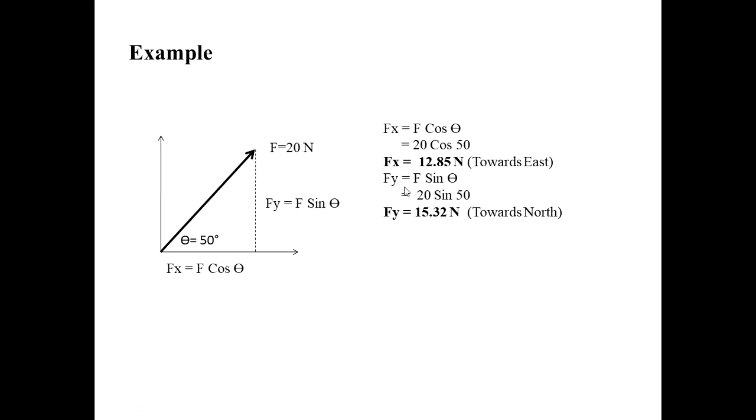Next, Fy will be F sin theta. So F will be 20, theta is 50, sin 50, and the direction of the force is going in an upward direction. So Fy will be 15.32 Newton and the direction is towards north.